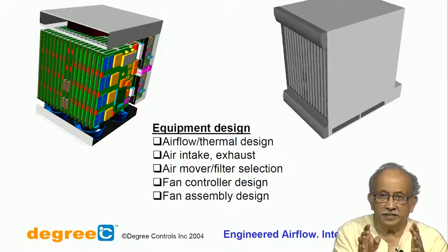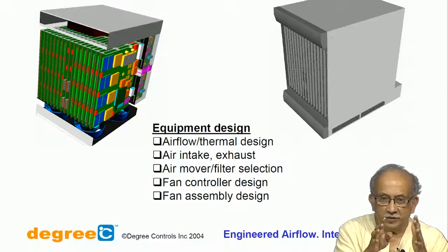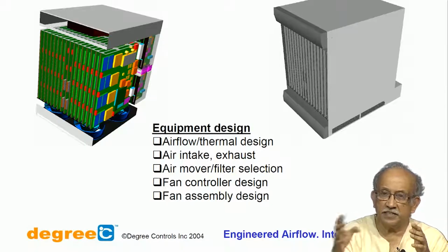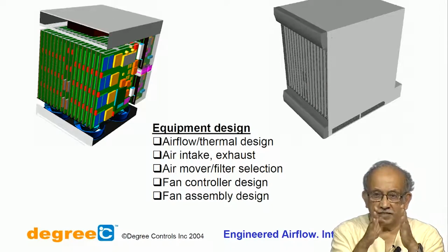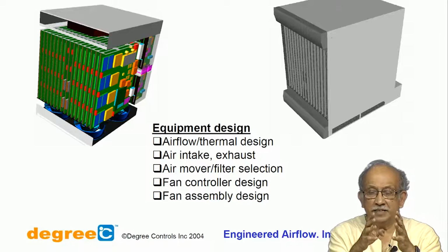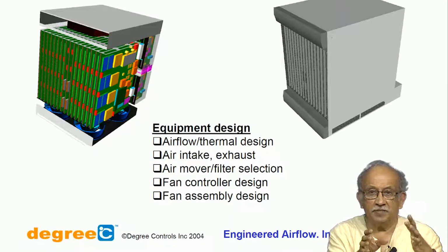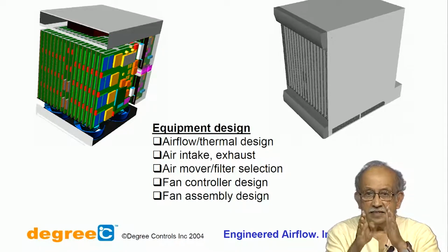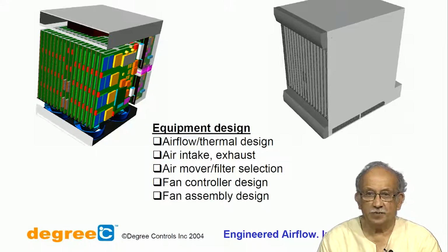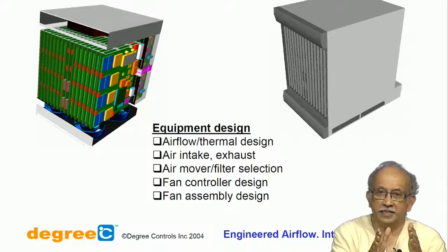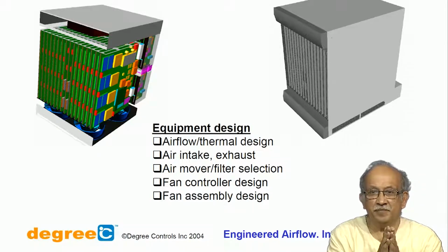So, what they do is one or two of them, usually the coarse filter can easily be dusted off, and maybe depending on the construction of the main body filter, that also you can probably disassemble and dust it off. The last fine filter is usually discarded. So, these are typically cassette filters which specialty companies make, but all this leads to tremendous pressure drop.